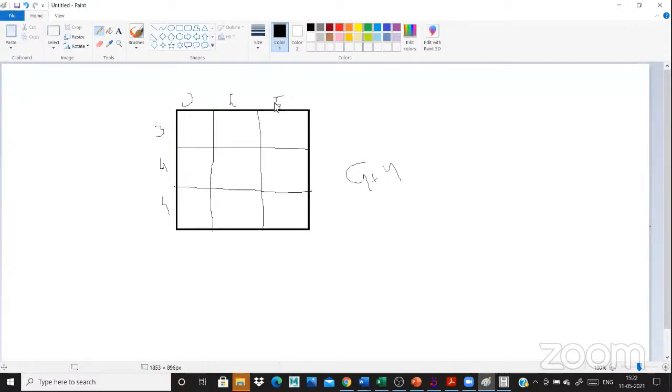Okay, today we will create the same model, G plus 4. This is the length, this is the x-axis. The x-axis has 3 bays. One bay is 3 meter, another bay is 4 meter, another bay is 5 meter. The width portion also has 3 bays. One is 3 meter, another is 4 meter, another is 4 meter. And G plus 4 floors are there.